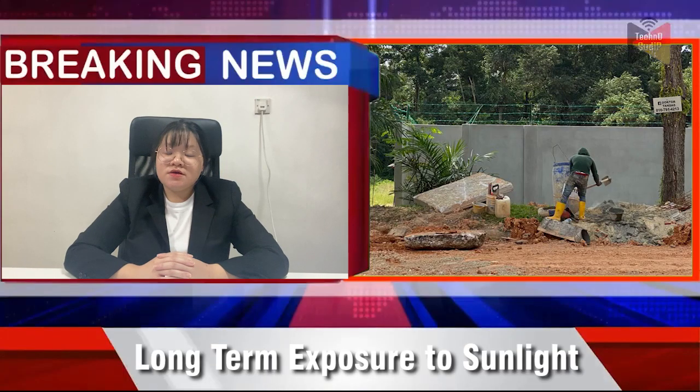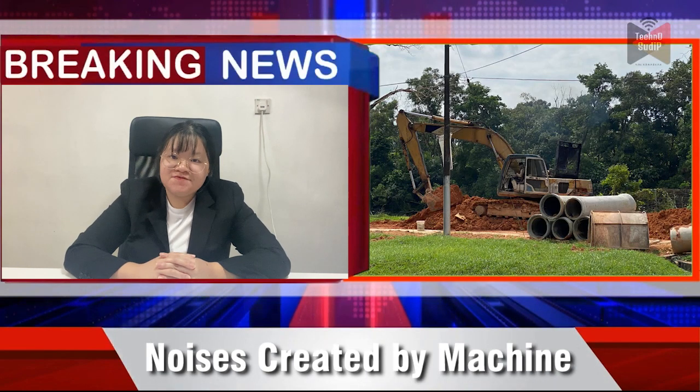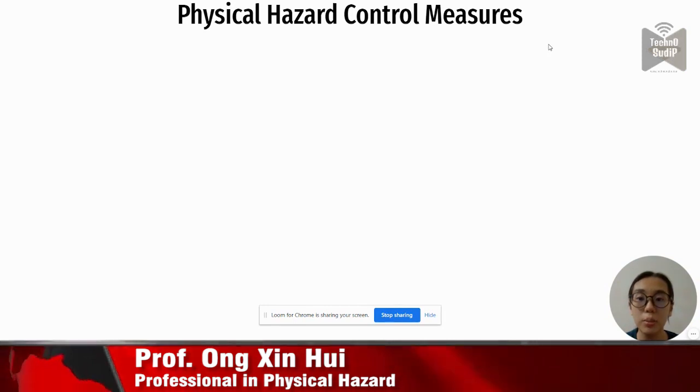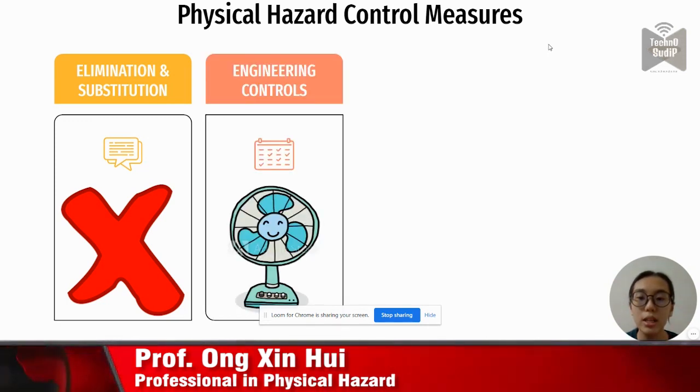Thank you. Workers working under hot sun can cause sunburn and skin cancer. Loud noise is also often heard at the construction sites, and these are the physical hazards. Let's welcome Prof. Ong to talk about how we should control. Yes, Reporter Wong. For the physical hazard control measures, elimination and substitution is not possible as it is difficult to eliminate sunlight. Engineering controls then can reduce incident of heat-related illness.